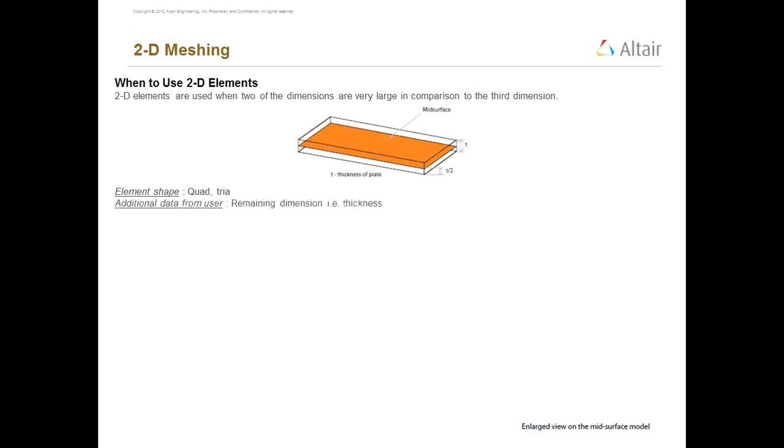As you can see, the thickness is given as a user defined value. Then the element types available in HyperWorks are thin shell, plate, membrane, plane strain, plane stress, axisymmetric solids, etc. Practical applications are sheet metal parts, plastic components like instrument panels, etc.